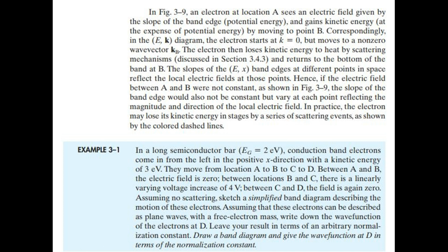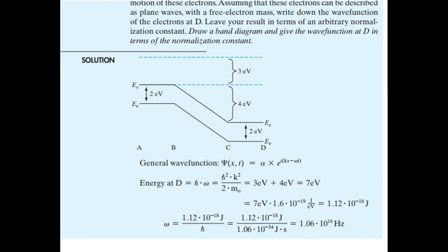Effective mass. The electrons in a crystal are not completely free, but instead interact with the periodic potential of the lattice. As a result, their wave-particle motion cannot be expected to be the same as for electrons in free space. Thus, in applying the usual equations of electrodynamics to charge carriers in a solid, we must use altered values of particle mass. In doing so, we account for most of the influences of the lattice, so that the electrons and holes can be treated as almost free carriers in most computations.